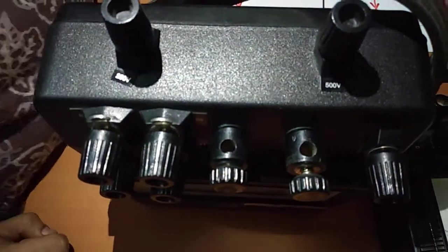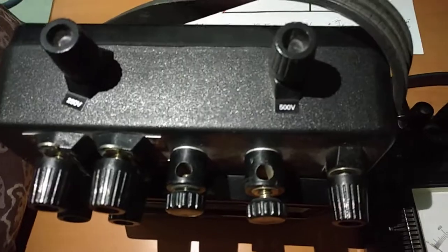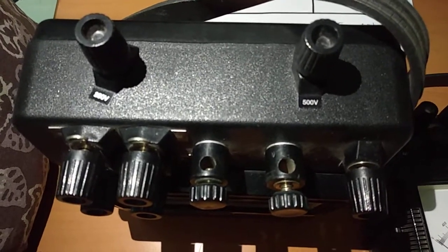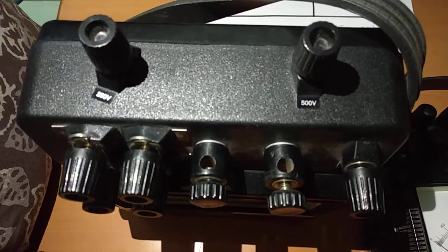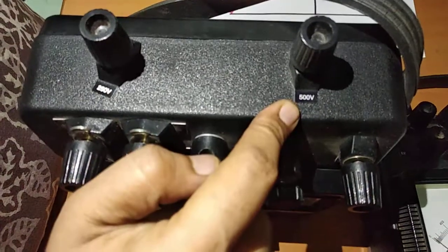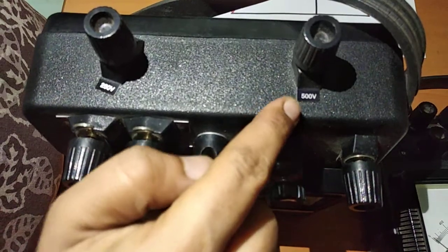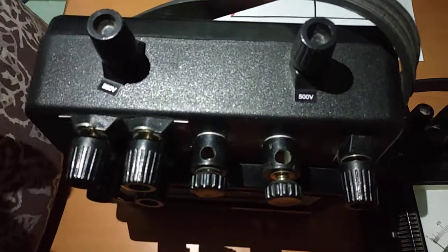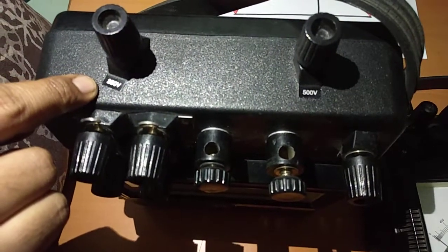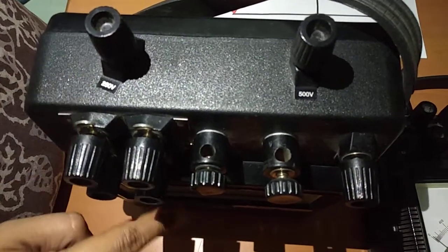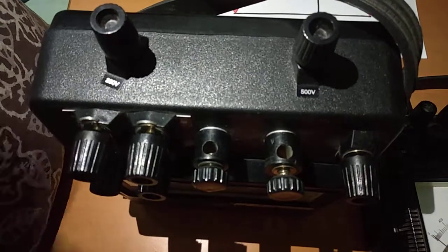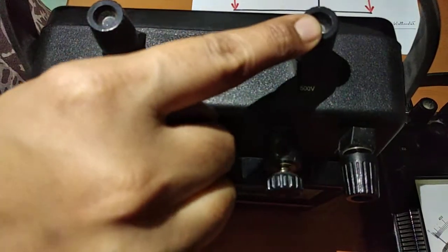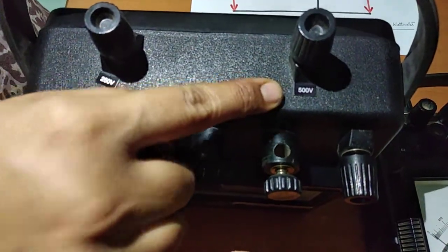In this particular experiment, we are going to use it for 3-phase measurement. And that will come up to 415 volts per line, isn't it? So we are going to connect it for 500. Always remember, measuring instruments must be used which are greater than the actual rating of the device. If I use 250 volts, it will unnecessarily damage the device, that is the wattmeter, and also spoil the circuit's behavior. So the V range that we use in this experiment is 500 volts.